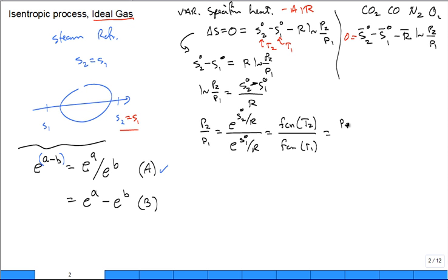They call it PR, and you evaluate that PR at temperature 2, and this is PR at 1. What is this PR? It's a relative pressure. It's not the reduced pressure, it's a relative pressure. It really doesn't even have much of a name. It's in the tables, though, for the air table, to help you do isentropic calculations with air.